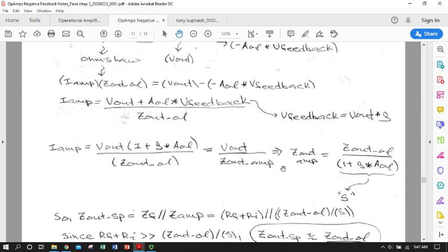So in the closed loop condition with series parallel negative feedback, the contribution of the output impedance from the amplifier itself, not from the feedback network, just from the amplifier itself, is equal to whatever the open loop output impedance of that amplifier was, which we can look up on a spreadsheet, divided by the sacrifice factor, otherwise known as the loop gain. This is cool. And remember, this is in parallel with our feedback resistance, so the effective total output resistance is going to drop even more because we actually have those 2 paths to ground.